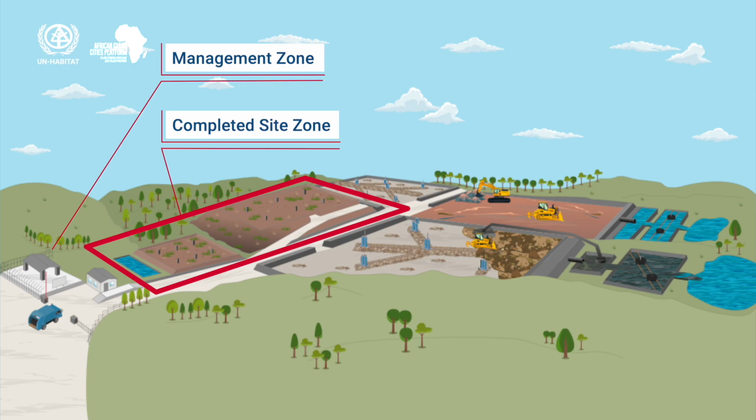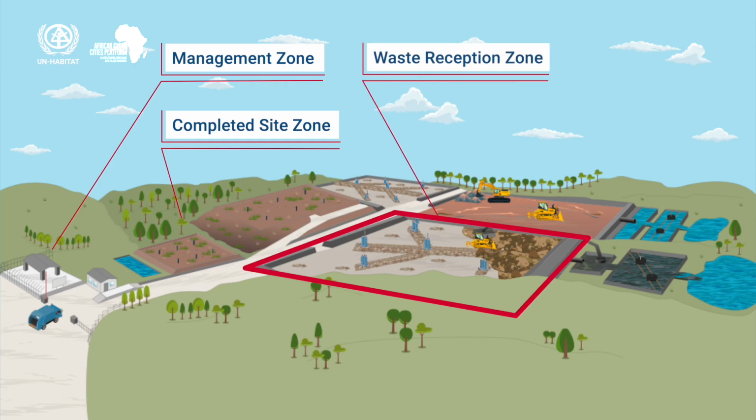The only evidence of this being a landfill are the vertical gas wells sticking out from the surface and the engineered side slopes. These indicate the presence of waste below. This is the ongoing daily waste reception zone. We can see the newly established cells that have the leachate pipes and vertical gas wells in place. There's a well-maintained site road leading to a waste drop-off point. Machinery pushes, layers and compacts the waste into place around the gas pipes before cover soil is applied.